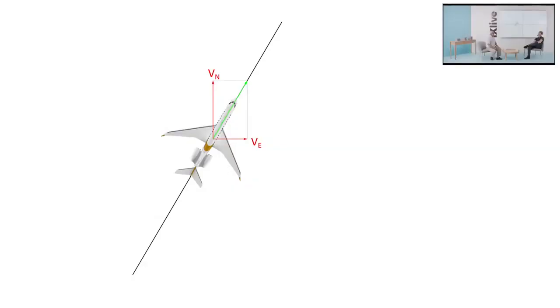We call this the observability of these parameters. And one of these parameters is the heading error, which cannot be estimated when the trajectory is a straight line at constant speed. Really? Well, this is strange because if I have a GNSS antenna, I will have those several points, and it makes the heading. That's right. This is the usual way to think about it.